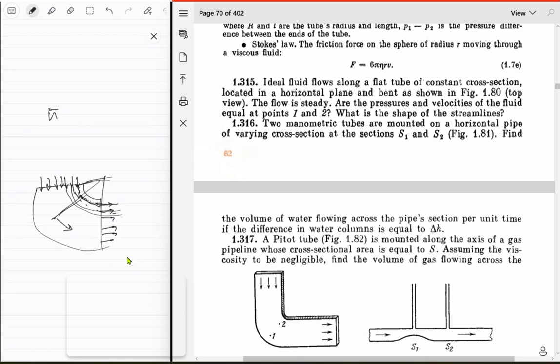So you just have u vector equal to u t hat. That's the distribution that you have, right? Okay, and of course there's the equation del dot u equal to 0, so that should be satisfied. And at the same time, okay, there's no viscosity, but there could still be vorticity, so Bernoulli's equation might not be true. Who knows? Yeah, there could be vorticity, right? Of course. And I don't want to get the curl and the divergence operators in the r vector thing. I really just don't want to do that.